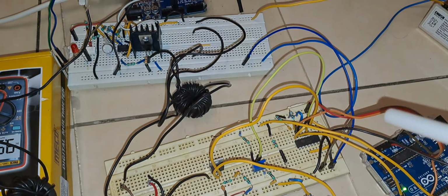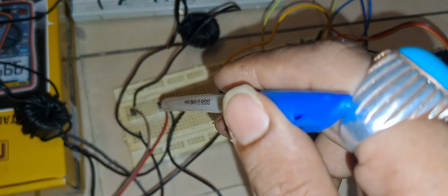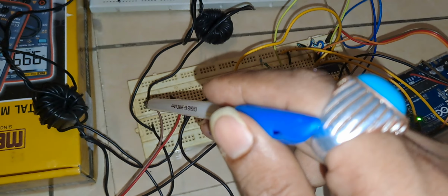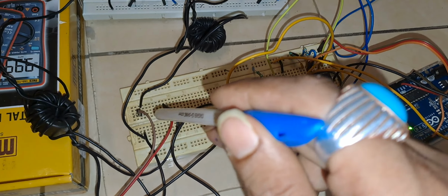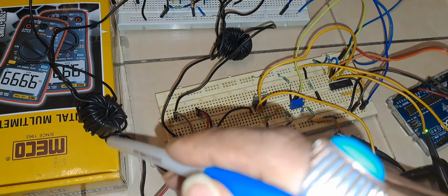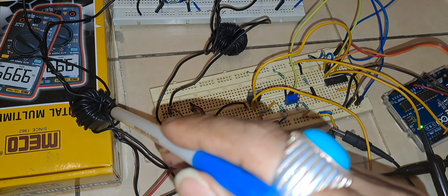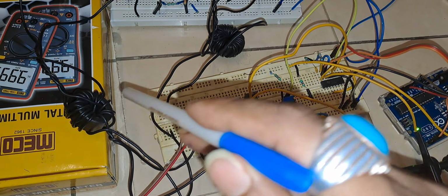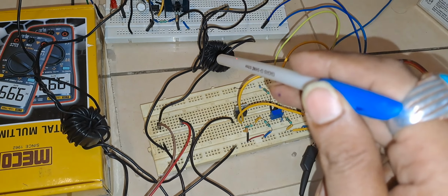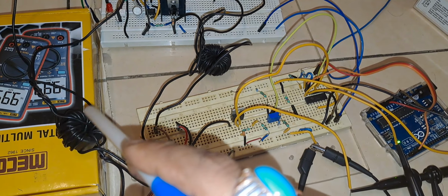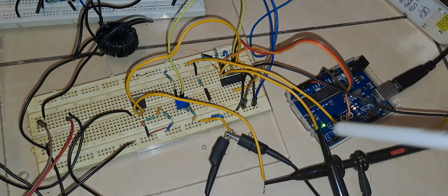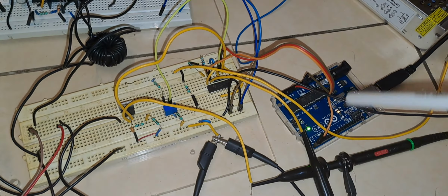And you can see here there is power line input at this point. I am feeding the power line at this point. Here you can see these are the two wires for the power line. The transmitter coupling transformer is in series with the power line and the receiver coupling transformer. This is the receiver coupling transformer. The data from the transmitter coupling transformer is received by the receiver coupling transformer and finally it is fed to this receiver unit. You can see this is the receiver unit.